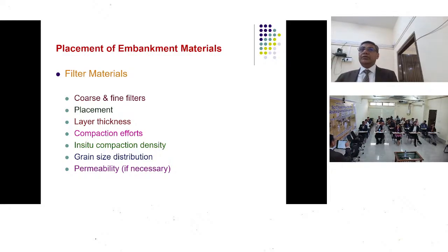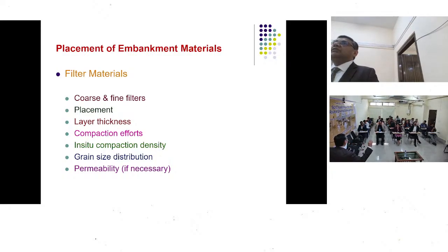So, as a quality control personnel, if we are posted there, it is a very continuous process that we have to do. Rather, you have to create a timeline wherein you will be fixing, okay, 12 o'clock we will be taking a sample of the filters, 2 o'clock we will be taking a sample of the clay core, 5 o'clock we will be doing an in situ density of the filters, and this time we will be doing a density at the clay core, and the clay core sample will be taking 2 to 3 days for the whole grain size distribution. So it will be after 3 days that you will be able to pass this layer.